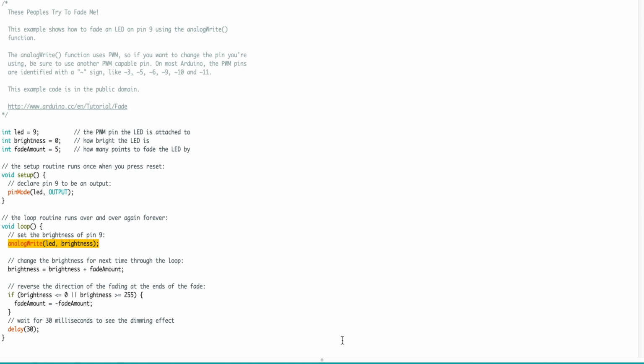The analogWrite call is on a scale of 0 to 255, such that analogWrite 255 requests a 100% duty cycle, as in always on, and analogWrite 0 is a 0% duty cycle, always off. And an analogWrite 127 is a 50% duty cycle. Why is it 255?